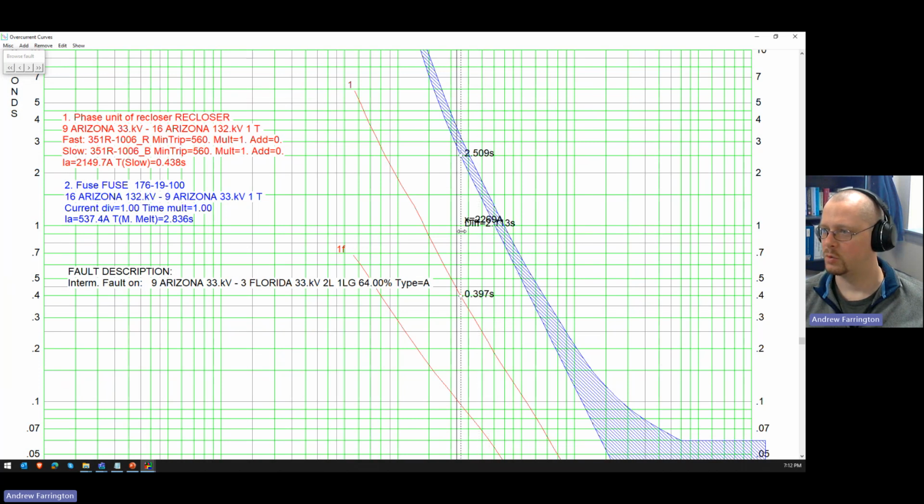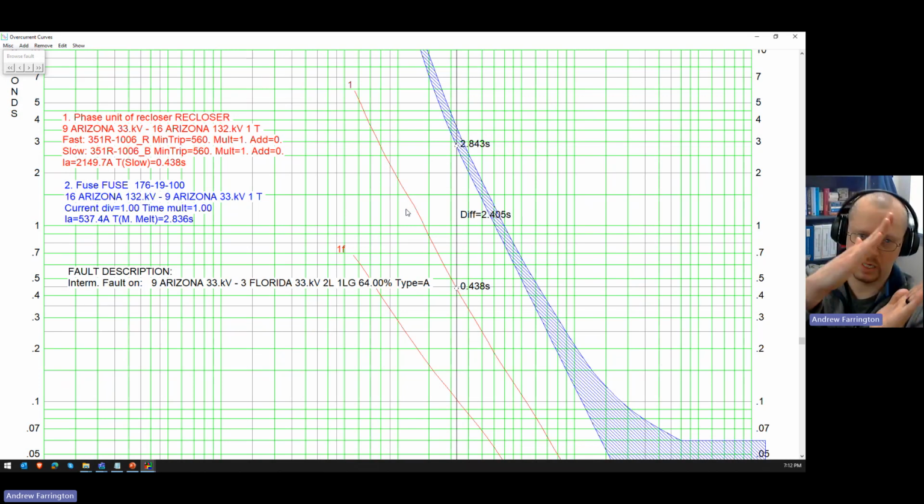What's the lowest CTI? Obviously, as these curves are diverging, as they're going up a log scale, we're getting much bigger CTIs as we get lower and lower fault current. So what I would be looking for, having observed that, is the maximum amount of fault current that both of these devices would see, or even better, the maximum fault current that this fuse would see while this is seeing the minimum amount of fault current that it would see. And that would tend to squeeze those down, that would shift them together.